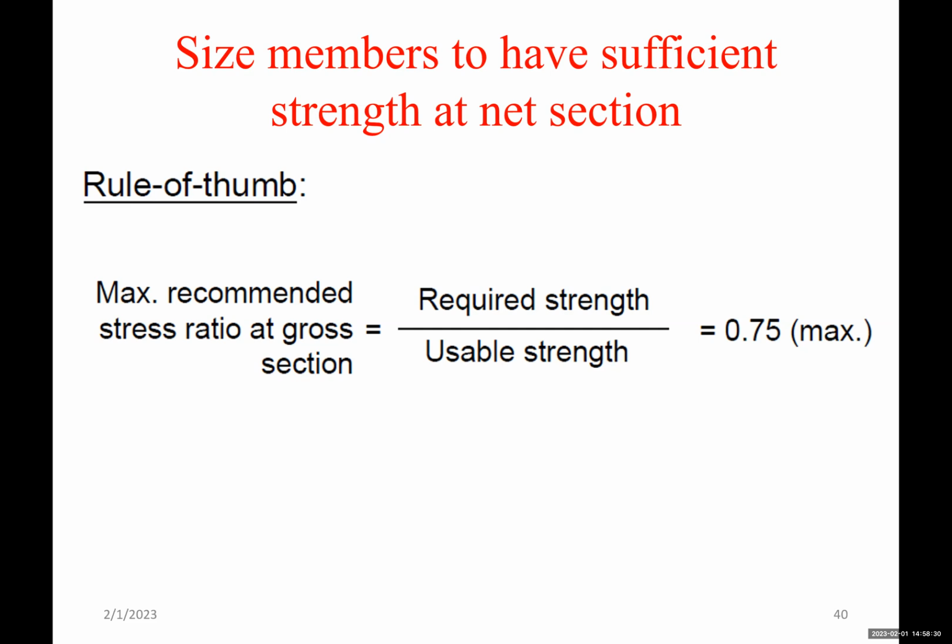So it's okay for bending and for shear, but when we come to the connections, there are holes in the beam, or in the brace, that will give us a net section. It could be beam, could be brace. So we have to check the member for that net section, for tension, if it's a brace, for example.